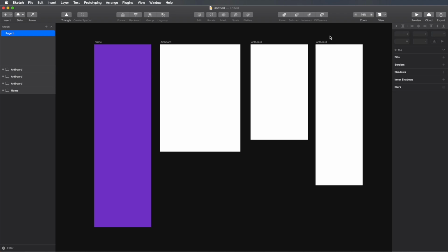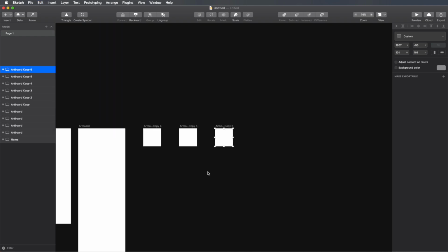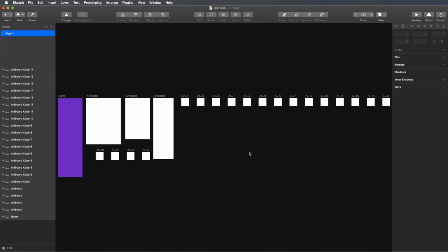So it really depends on what you're doing, but the artboards is a very, very useful feature. One other use, when creating icons, you can have an artboard for each icon. And you can have a whole grid of artboards, and each artboard will contain a single icon. Very useful for creating icon sets. So you can do a lot with artboards.